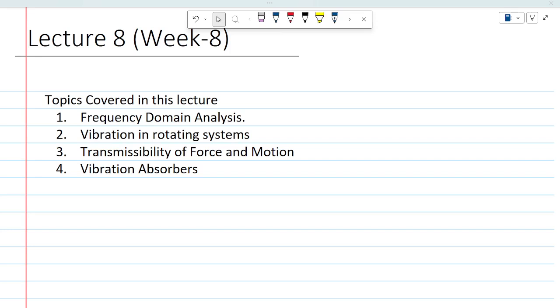And if you recall the topic we discussed before the midterm examination, it was about the transfer functions, Laplace transform, which was a technique to convert the differential equation of the mechanical vibration system into an algebraic equation, which makes it easy to solve. And then there's a specific thing in the Laplace transformation, a transfer function, which is a Laplace transform output over the input of a system. So mostly we do it considering the zero initial conditions, and then we can later on add the initial conditions in our Laplace transform function.